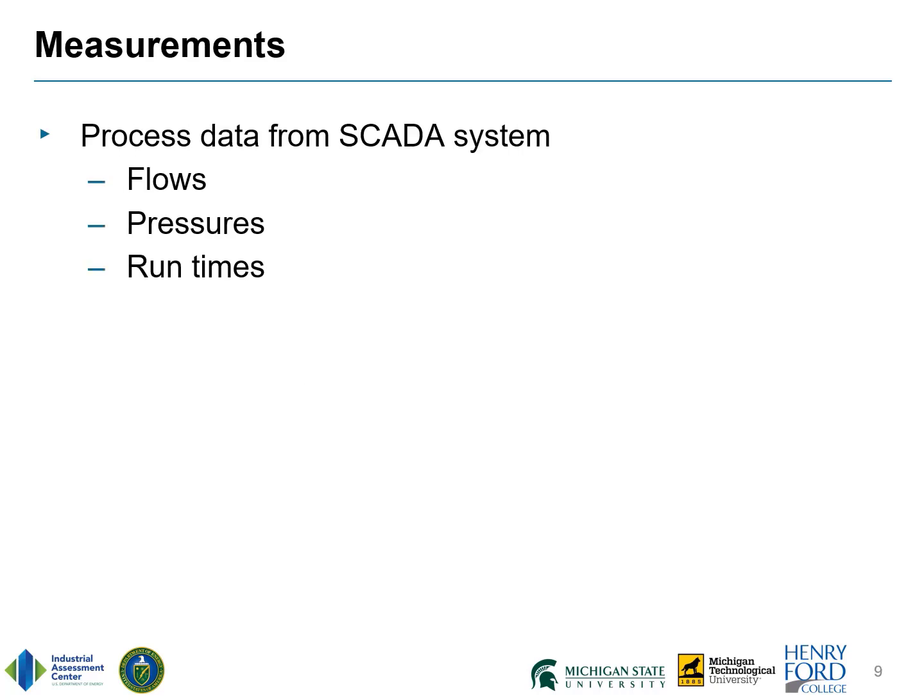The measurements taken during a site visit will vary. As previously noted, energy use for the wastewater processes is higher than for building loads. However, it's still necessary to record building information. Much of the process data may be available from the treatment system through the SCADA, mentioned previously, that's Supervisory Control and Data Acquisition System. The SCADA system should be recording flows, pressures, and the runtime for major equipment. Be sure to obtain as much of this data as possible for future analysis.